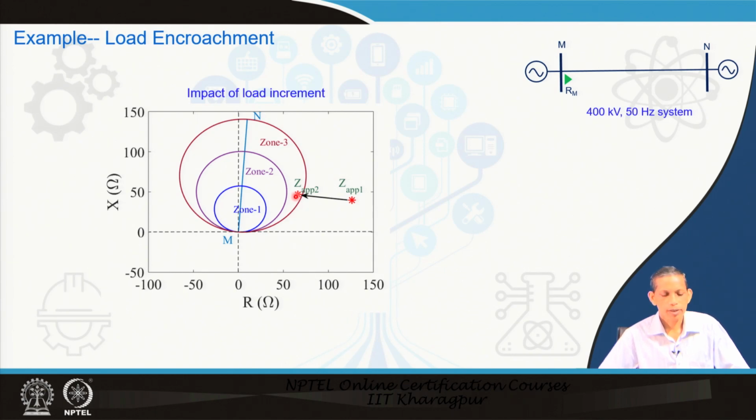So, what will happen in this case if the load persists for a longer period of time than the delay time set for zone 3? Then zone 3 will consider this as a fault situation and operate, pick up, and that becomes a malfunction. So, this is a security concern.